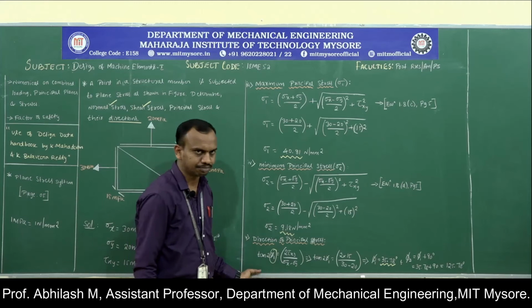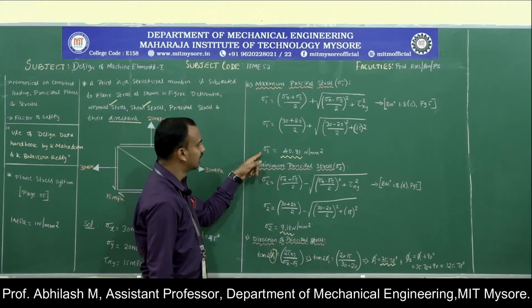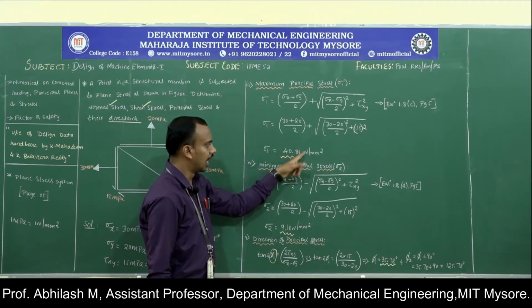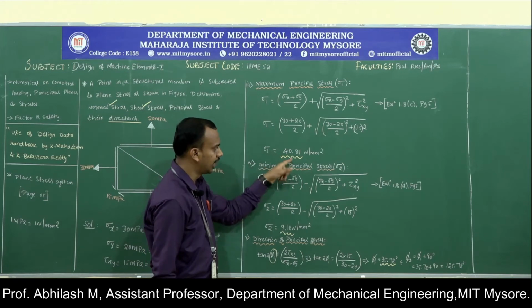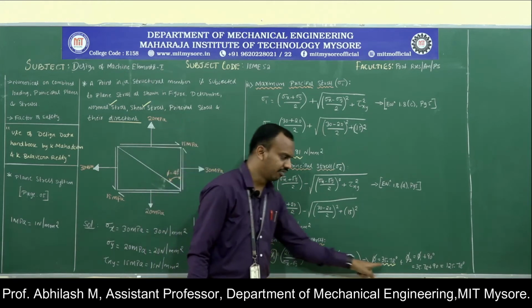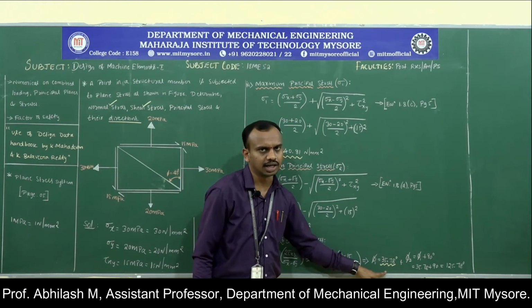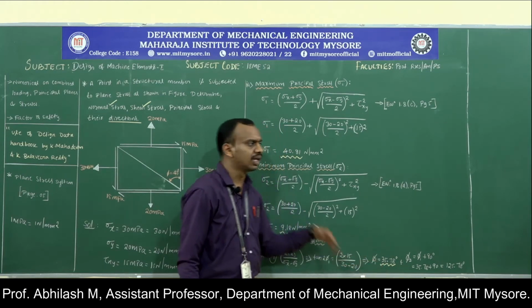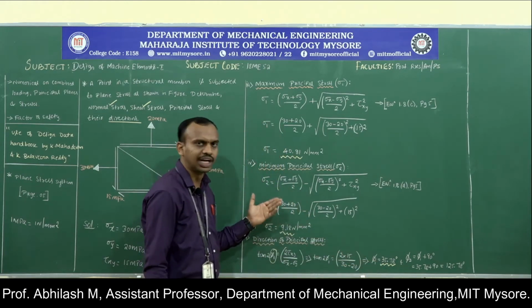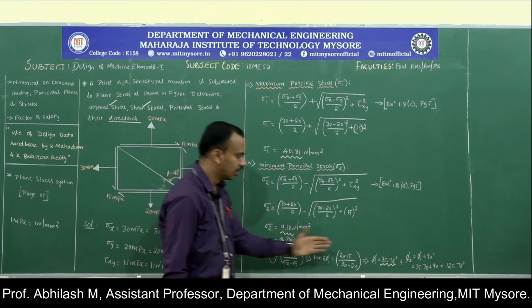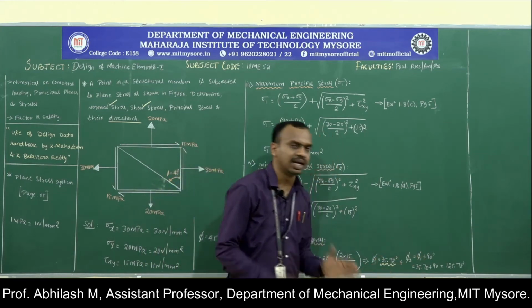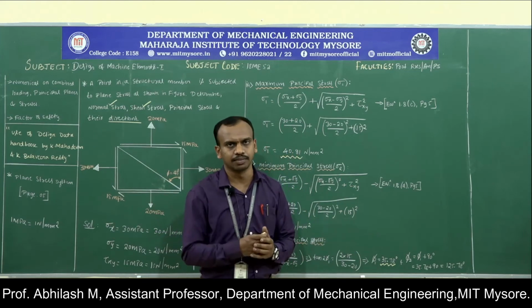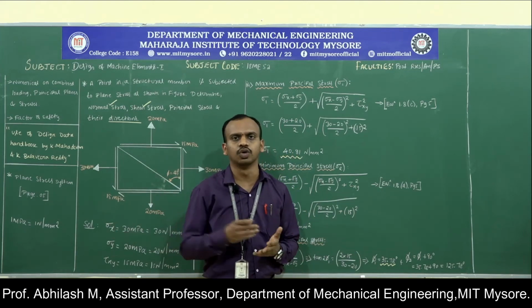35.78 degrees. So, the maximum principal stress, having a magnitude of 40.81, is acting at an angle of 35.78 degrees in the given condition. Then what will be the other value, that is phi 2? We know that phi 1 and phi 2 will be 90 degrees apart. The principal planes are mutually orthogonal to each other.